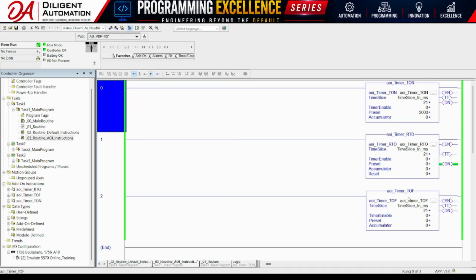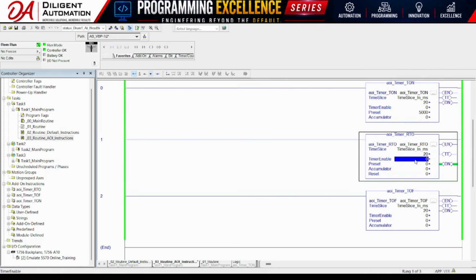Like our TON add-on instruction, this AOI also uses the time slice value that we calculated earlier. Instead of relying on the controller's internal timer, it accumulates the elapsed time by adding the time slice during each program scan. The main difference between a TON and an RTO lies in how the accumulated value is handled. Let's go through the logic step by step.